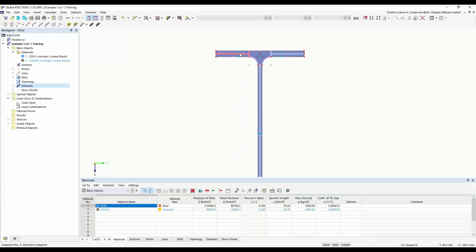What you can see here are the sub-panels, and these sub-panels are automatically generated based on the standard selected in the base data dialog, and these cannot be changed. If no elements are defined, the cross-section classification in our section and in the design modules of RFEM or RStab is not possible. And it's also not possible to do a calculation of the effective cross-section if no elements and no subpanels are defined. In the design add-ons of RFEM or RStab, like steel design, the cross-section is then designed according to the cross-section class 3.